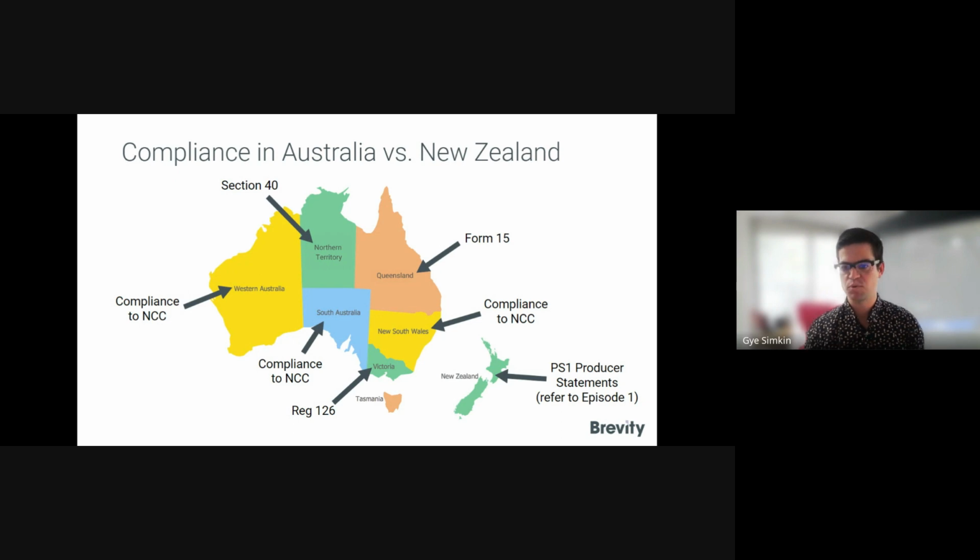And there's no simple answer to that question, because the seismic requirements need to be assessed in all cases against the other loading scenarios, such as wind loading, which, in Queensland for example, often governs. That is used to determine which is the governing situation.